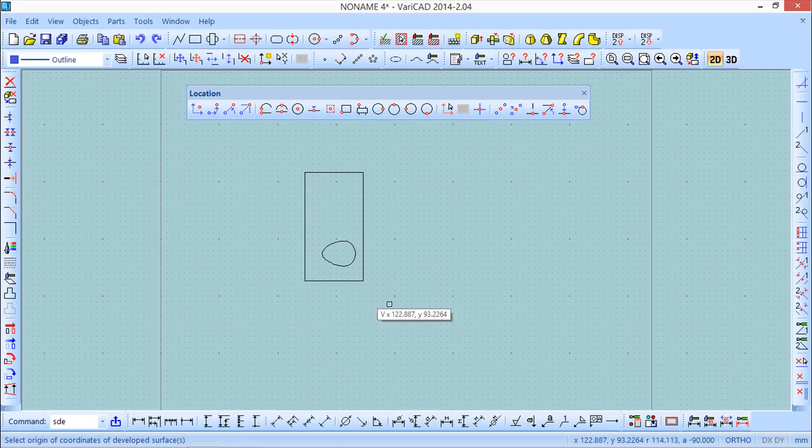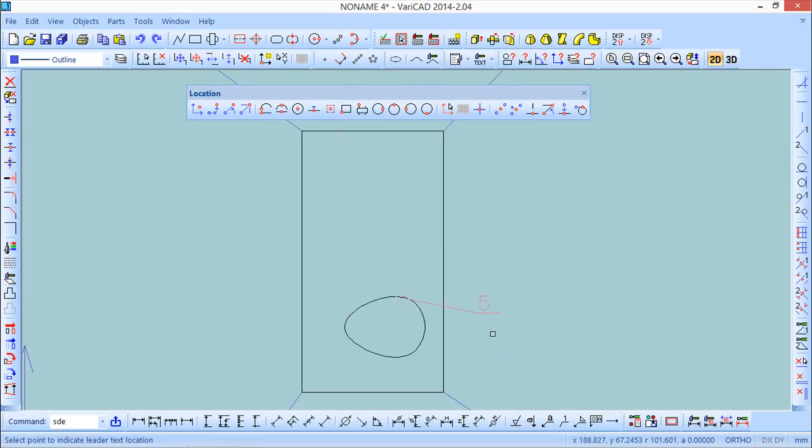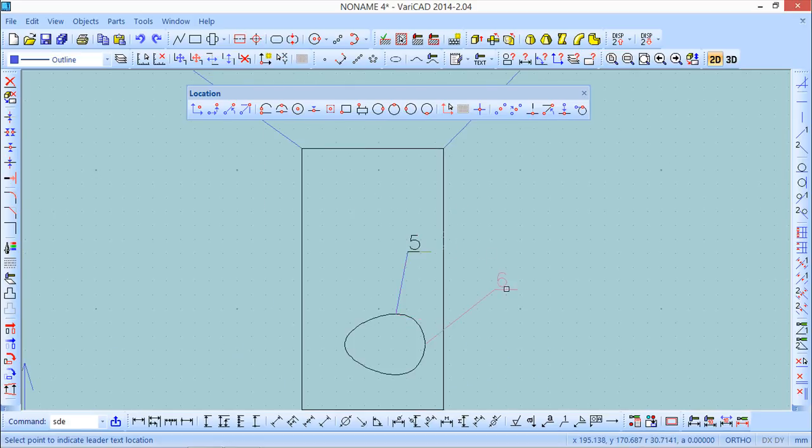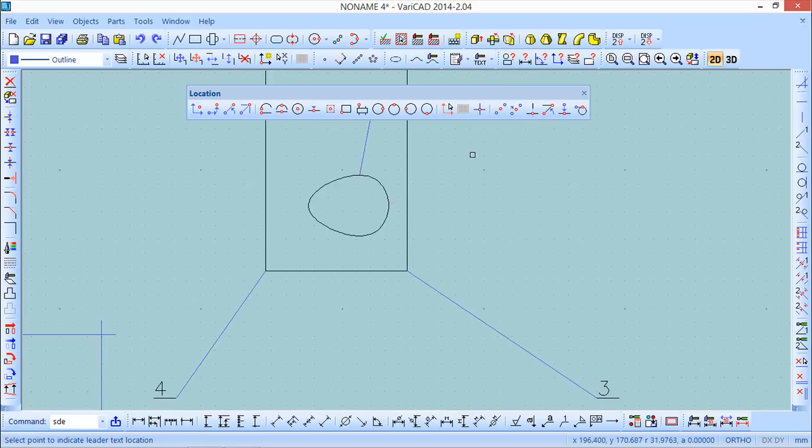So this is the solid. I can put the origin, for example, outside, and now, okay, that's what I want to show you. Now it's too big, but the idea is to show you the concept. So every 15 millimeters, that was what I chose, it will make an approximation of a segment between the 2 points. Okay, for sure 15 in this case was excessive. To have something accurate, you should probably choose 1 millimeter or something similar.